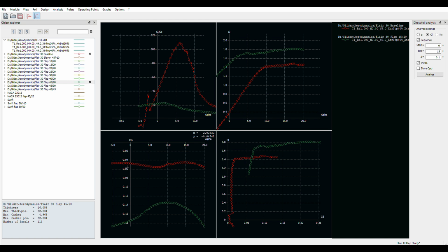It went from minus 0.047, I think is what we had, all the way to minus 0.17, yeah, not quite 0.18, 0.175. Huge nose down pitching moment. Now, does that mean that the elevons couldn't counteract this pitching moment? No, they have different moment arms on the aircraft. They have different areas. You got two elevons, you got the two flaps. I don't know. You would have to put in considerable up elevon in order to counteract this much nose down pitching moment. How much? I don't know.